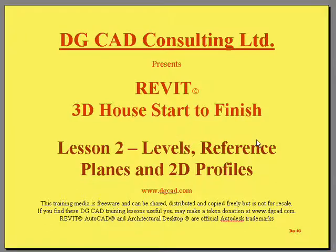And here we are in the second lesson of our 3D House start to finish project. Inside of this lesson we're going to be talking about levels, basically elevation lines. We've got reference planes, which are lines that run vertically through the building, and we use those to anchor our objects to. And we'll talk a little bit about working on some 2D profiles, which are going to help us to modify our wall styles out of the box with Revit.